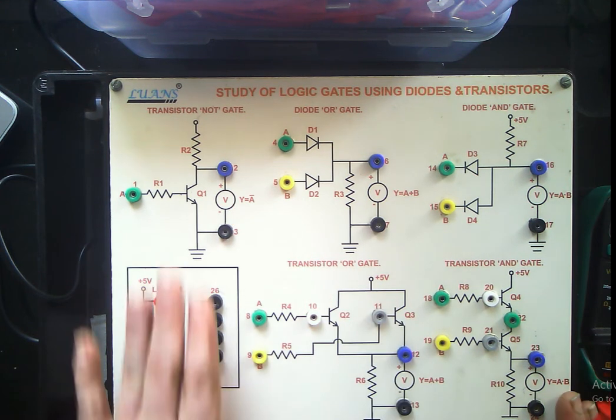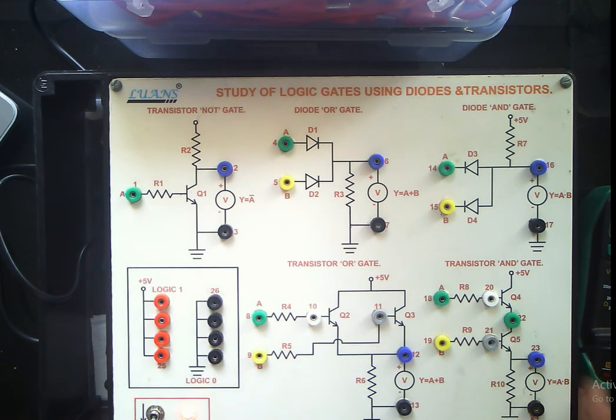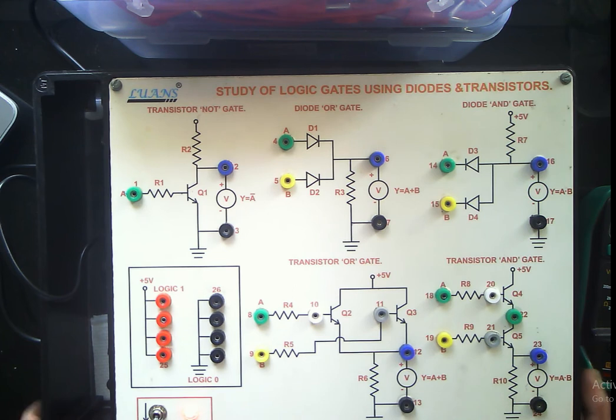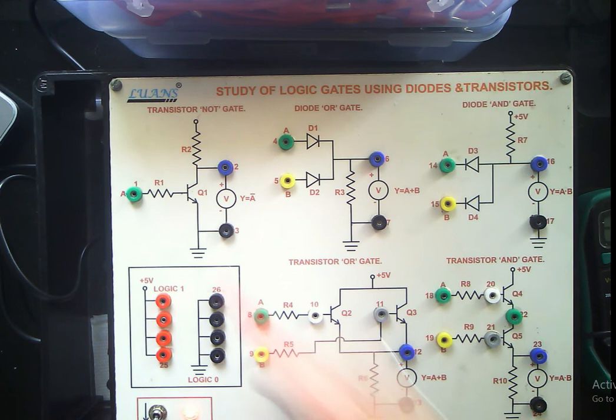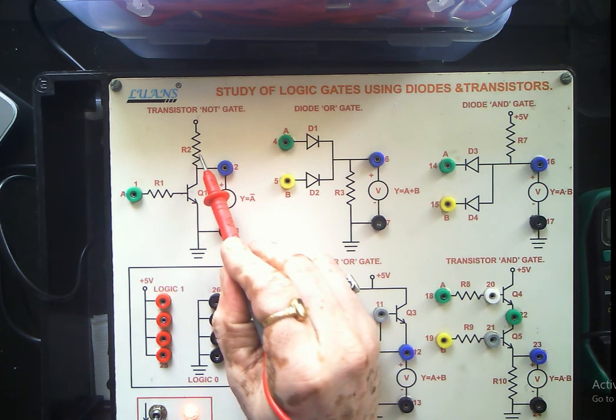Remember that this is the very circuit in which you are using the transistor simply as a switch. Whenever we are using a logic device, which is a low output current device, to drive some high current load, then the load has to be connected in the position of R2.